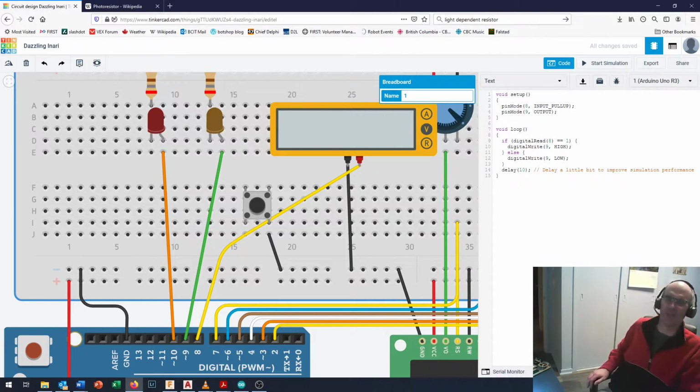the Arduino. You're setting things high or low, but when you're reading things, the switch is so common and the need for a pull-up or pull-down resistor is so common that they've built a pull-up resistor into the Arduino. They didn't build a pull-down resistor. Guess they figured it was easier to make the pull-up.